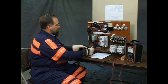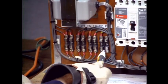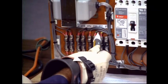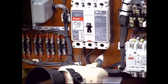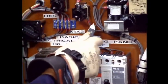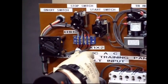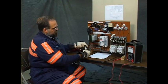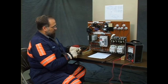Now we're going to check our circuit. That intermittent flash, that's a built-in test of the instrument to tell you that it's on, it's functioning. It's not to indicate power. When we have power, it locks on. You have the tone as well as a constant light. Just see that again. That's how it is with power. We didn't find that though.